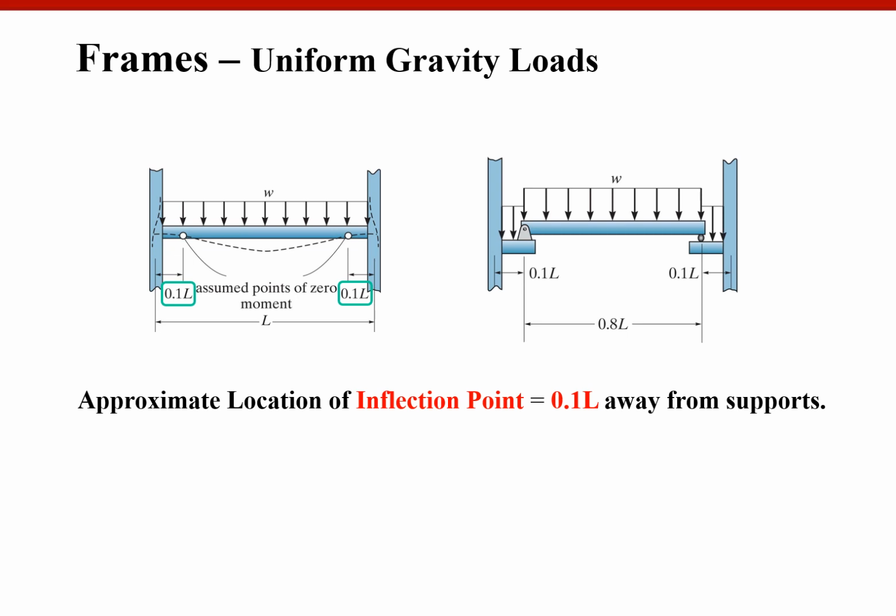I found two guys in the class who still do not know how to analyze a compound beam. I asked you to analyze the simple beam portion of the complex beam first, and then use the reactions of those simple beams as actions to the rest of the structure.